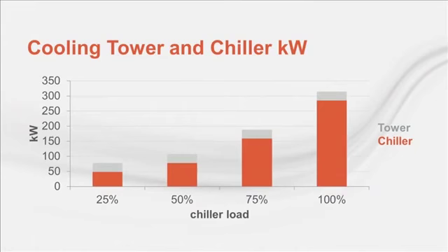The second mantra is that the cooling tower power is so small compared to the chiller that it doesn't seem to make sense to reduce tower fan speed in kW. At design conditions, that's usually true. But what happens as load and the temperature the tower can produce goes down? The tower becomes a larger percentage of the system energy use.